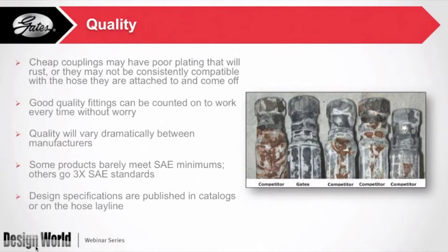However, on a hydraulic system, say a 2.5-inch 5,000 psi spiral hose that's going to be propelling a ship through the water, you want to make sure that that hose is going to work properly so you don't lose power or the ability to steer. So we want to make sure that we pick the quality that's going to meet the requirement for the job without spending too much money to get what we need done.